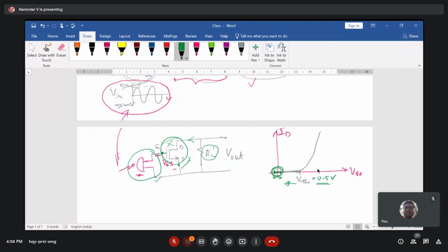This is the first attempt, in which we connected our analog signal directly to the MOS transistor without any biasing voltage, and we are trying to estimate the output. Connecting the input voltage directly as an analog signal doesn't put your MOS transistor into the saturation region of operation, and the device is completely off, so there is no amplification of your output voltage.